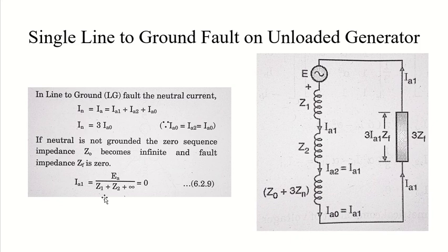And earlier, remember the circuit I was telling you about. So here is that circuit which I was telling you about. By the way, you can obtain the same result if the system is isolated from neutral, because there is no return path for my current, and because of that the value of all three symmetrical components will be 0.